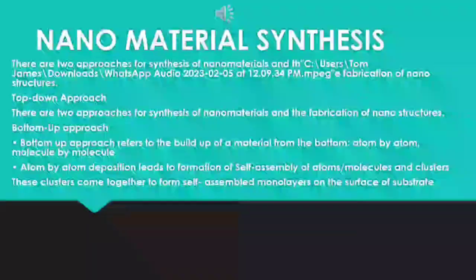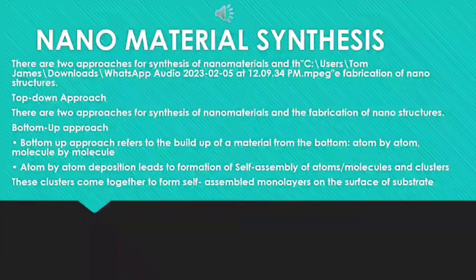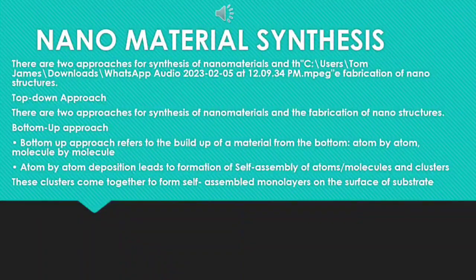Bottom-up approach. The bottom-up approach refers to the building up of material from the bottom, atom by atom, molecule by molecule. Atom by atom deposition leads to the formation of self-assembly of atoms or molecules and clusters. These clusters come together to form a self-assembled monolayer on the surface of a substrate.